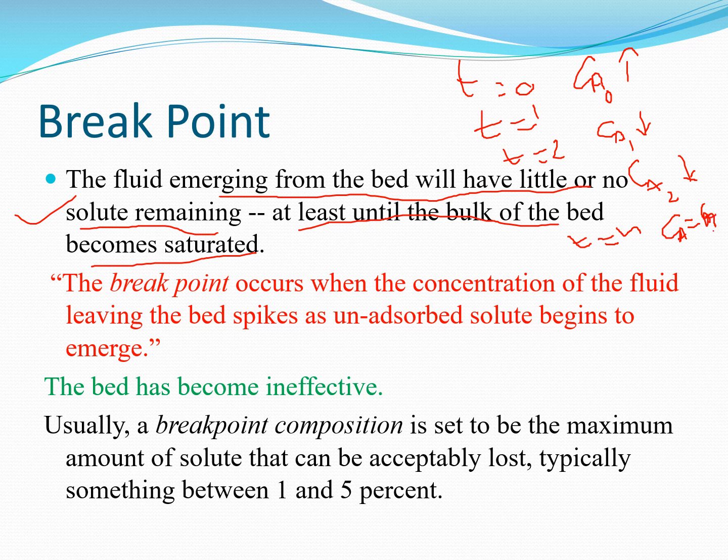That means now the adsorption, how much adsorption takes place, it's completely saturated, and now again the exit stream has the same concentration as the entering stream. So this is basically a break point, where the concentration of the fluid leaving the bed spikes as unadsorbed solute begins to emerge.